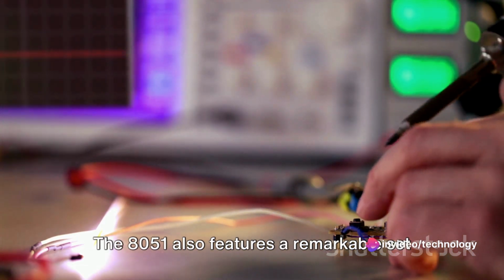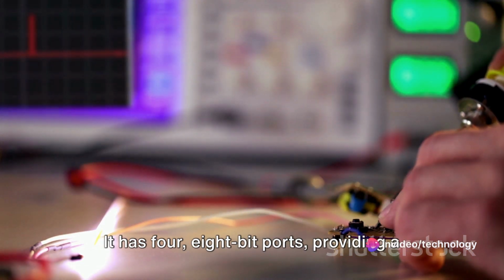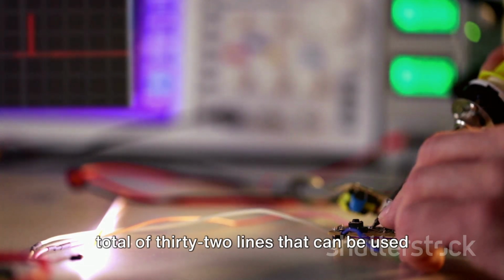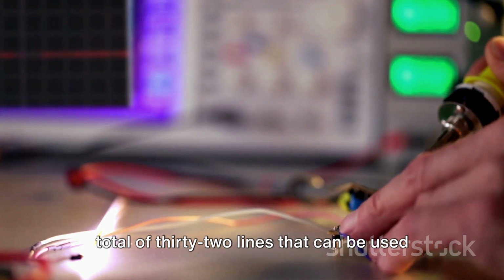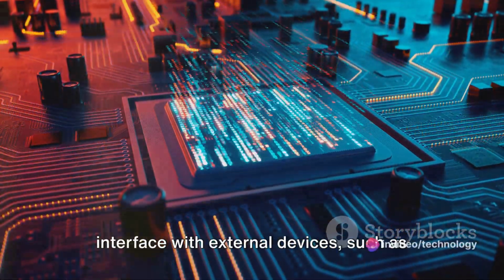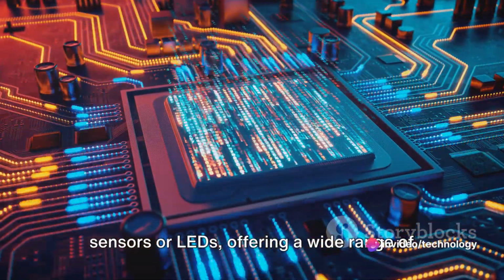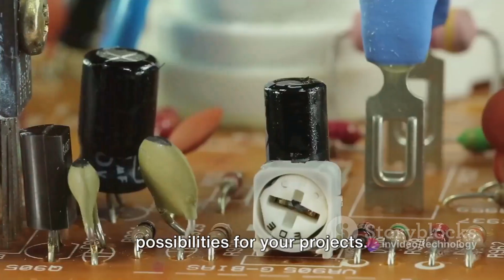The 8051 also features a remarkable set of input-output ports. It has four 8-bit ports, providing a total of 32 lines that can be used either for input or output operations. These ports can be programmed to interface with external devices, such as sensors or LEDs, offering a wide range of possibilities for your projects.